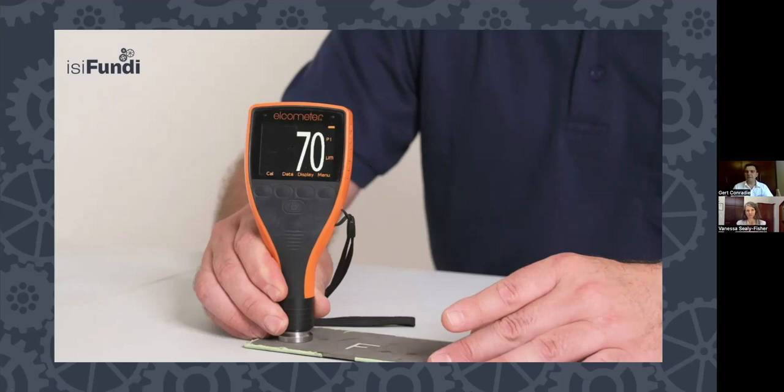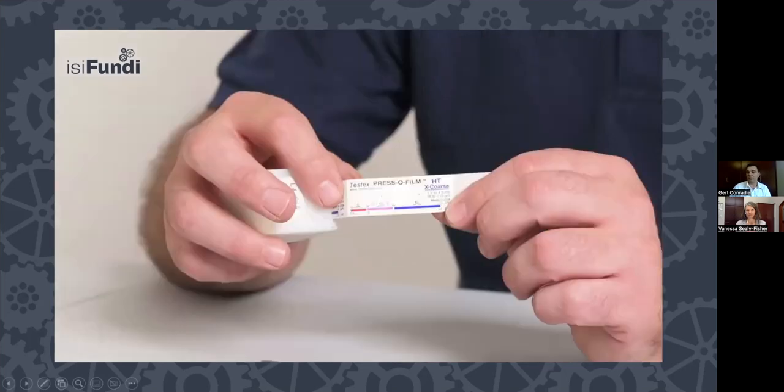But then they started picking up in the industry, because you are taking peak values and you're taking valley values, it's not a true representation of what the deepest valley is or what the highest pit is. So the new method of measurement is doing exactly the same, taking 10 readings, doing it 3 times, so that's 30 readings, but only recording the highest value that you achieved in each set of 10 readings. And by doing that, you now get to your third method, method C, according to ASTM D4417, which is using replica tape.